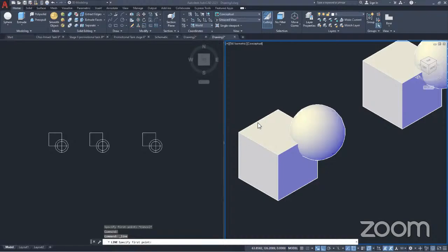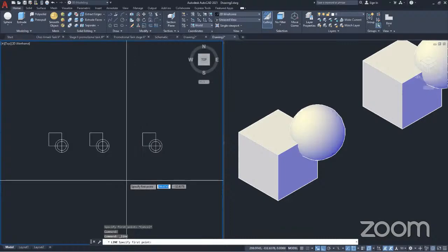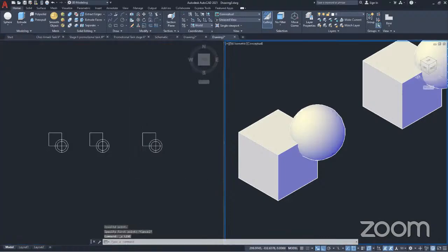I have a big issue now. Okay, so just Ctrl Z. Let me draw a line and press pull it, rather than extrude, because you cannot extrude a line. Let me press pull this line.